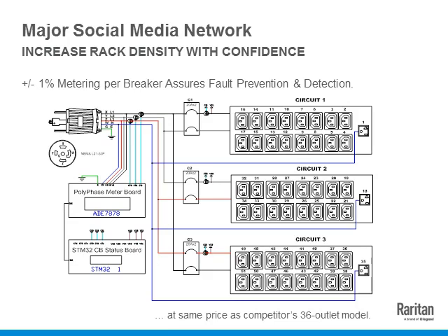Now, if you multiply that by the hundreds of racks they have, that's quite a lot of capacity that's left unused, which you already have, you're already paying the co-location provider for, but not utilizing it. So that's how we came up with the solution to closely monitor these circuits and take actions based on it anytime the load goes over a certain threshold.